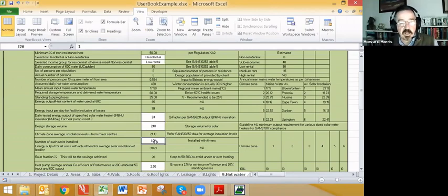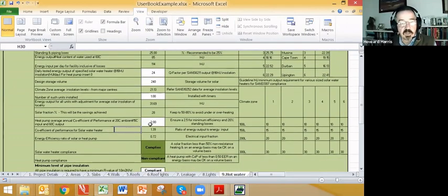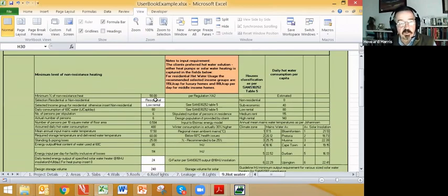We need to enter the 1 there, and then we need to discuss the possibility that this house has a heat pump installed. We are using the same volumetric determination, and then just assuring that we have a value of more than 2 installed. With wastage, it would need to be grossed up to a COP of 2.5 to ensure that we are getting more than the 50% minimum non-resistance heating achieved.